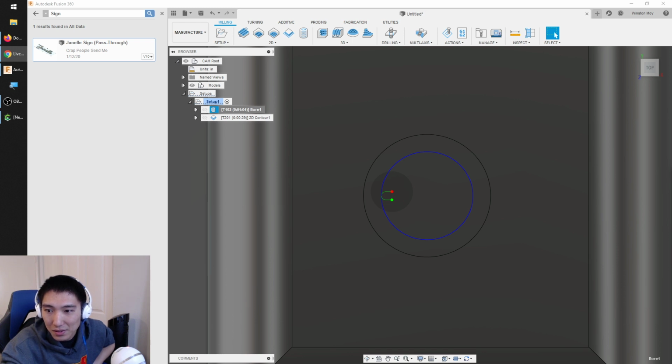Let's see. I was trying to reduce chatter in a pocket operation with a 1/4 radius end mill. Should I add more depth of cut and lower my feed rate? Reducing depth of cut and reducing feed rate will both reduce the forces on your spindle, so that's a good way to just back off in general. Other things you might want to try is to reduce step over, and potentially use adaptive clearing if you're comfortable with Fusion.